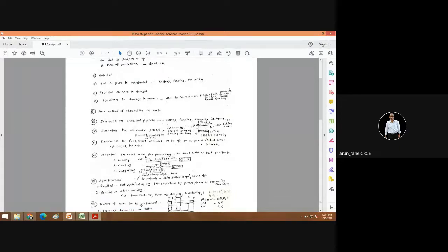So what are the different processes to achieve this 25H7, 25 plus 0 plus 18 micron? Obviously drilling is not possible. You have the option of reaming. You can do it by a finish boring operation, that is, using a micro boring tool. You can interpolate also on milling machines, but with interpolation you may get out of tolerance, or you can broach it. So these are the different alternate processes. Not this, not this, not this. Like when you go to a hotel: what is this, no, what else is there, what's the third, like that.